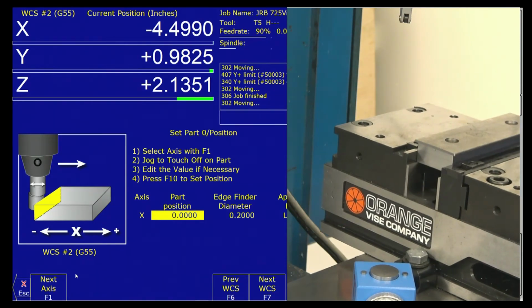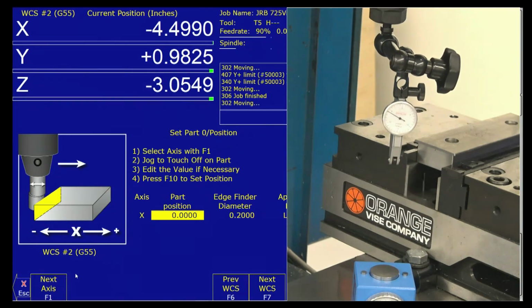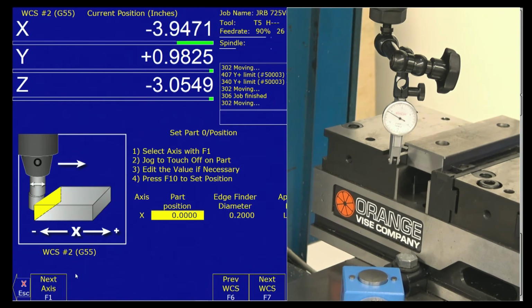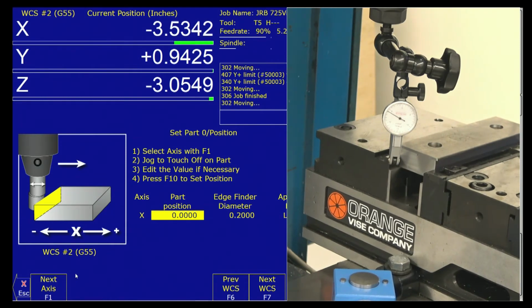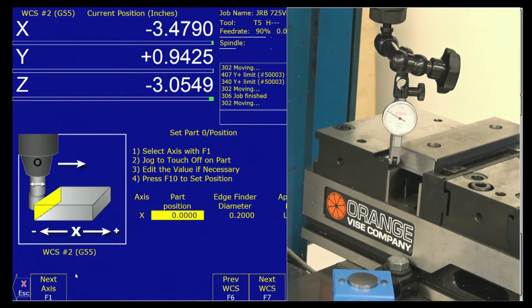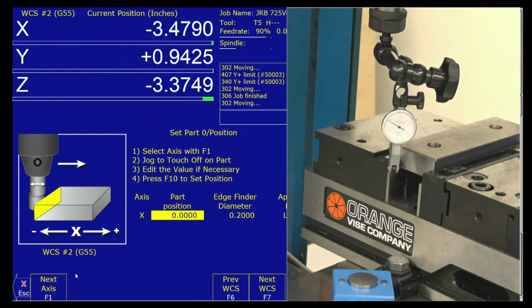Making a big deal out of that because so far, every time you've set it on top of your part. So when we go to program, we need to remember this. Going off the parallel. We're going to have to write our tool paths with Z0 under our finished part. And we'll rediscuss that when we get down to programming.